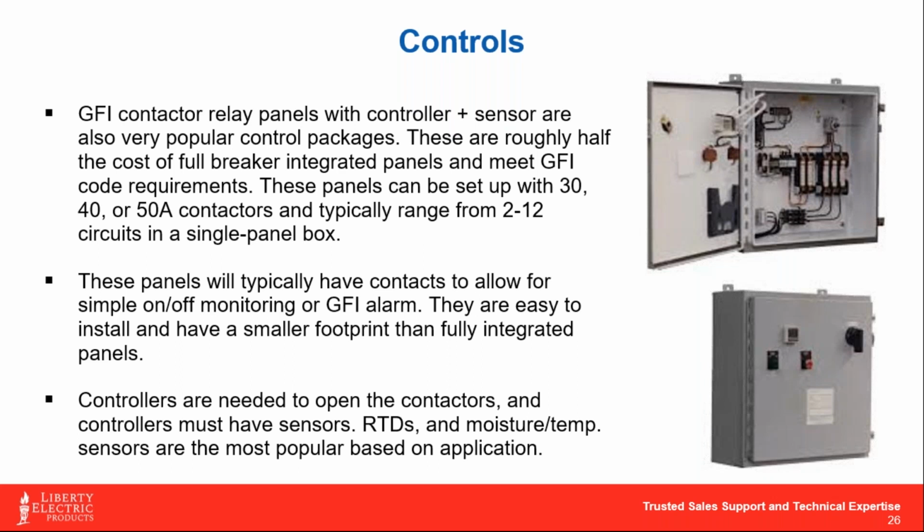So what was in the pipe or the skin of the pipe may not have cooled down to a point where the heat trace really needed to be kicked on. So when you look at skin temperature, we like that because it's a lot more accurate and it's more efficient for your system overall. Okay.